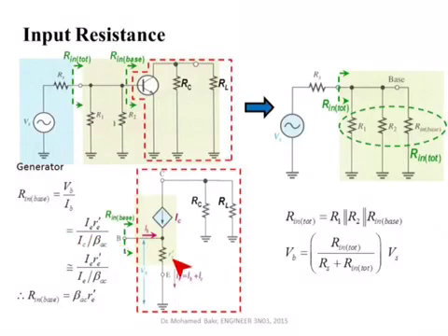We know that I emitter, even in the small signal case, is equal to I collector plus I base, which exactly holds also for DC analysis. But I know as well that I base is much smaller than I collector and I emitter. So for simplicity, I can assume in this expression that I collector is equal to I emitter. By doing that, I can remove I emitter from the numerator and denominator.